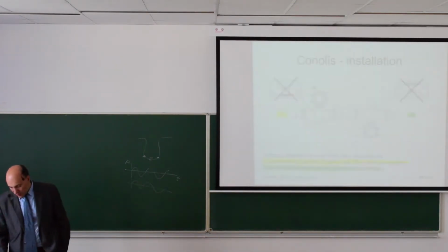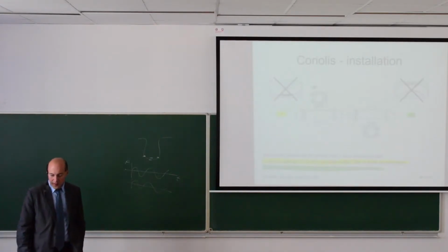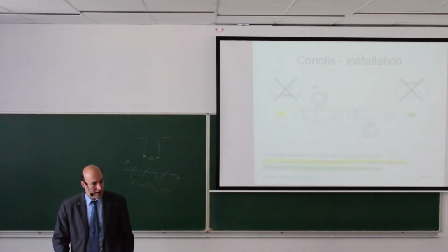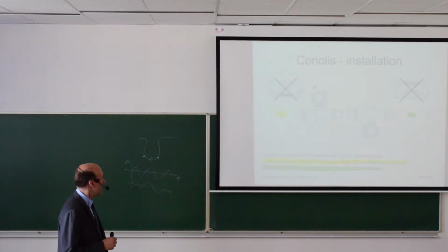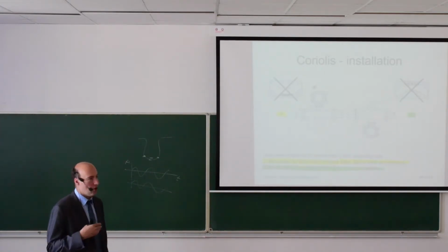So how to install the Coriolis flow meter? You should install it in such a way that it remains full at all times.